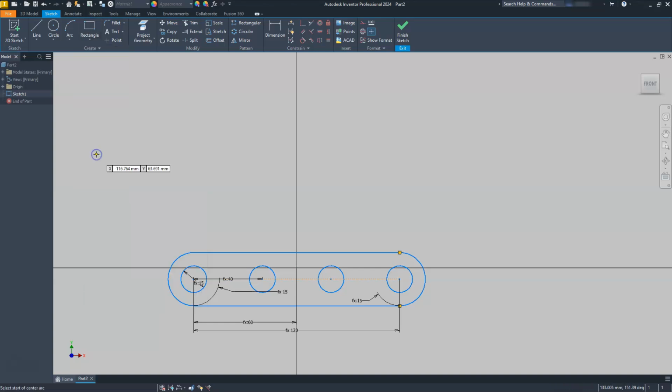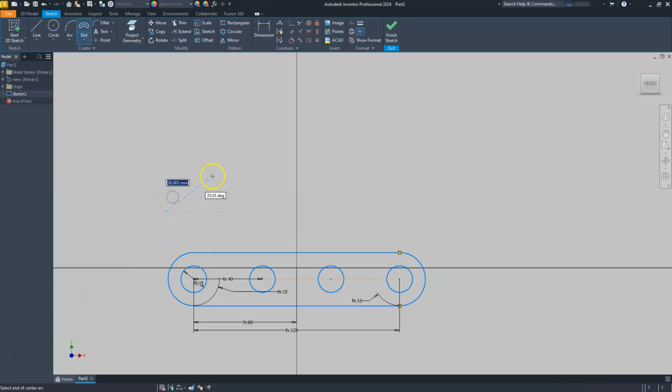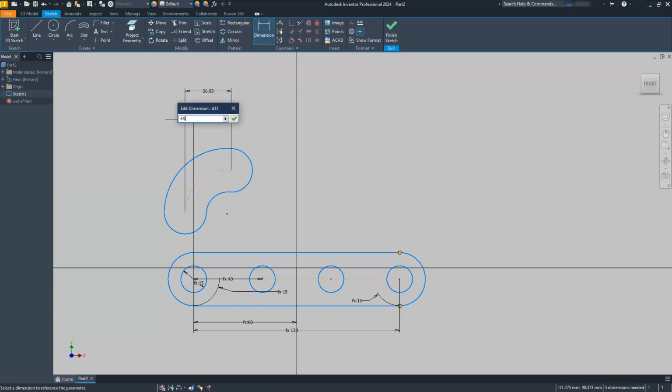So I'm going to select this 3-point. I'm going to click here. Let's see, somewhere along here. I kind of got to get it somewhere in the middle here, right? And then I'm just going to blow it up that way. All right, so I'm going to start locating where my centers are. I'll go back to the dimension. I know that from this center point to that end point here has to be 5. I know from this end point, so I'm just clicking that end point to this end point, has a distance of 65.